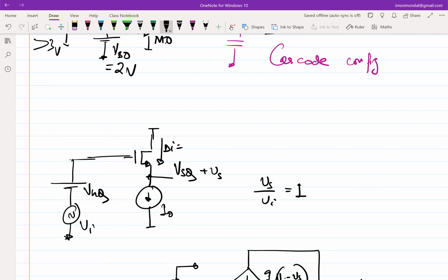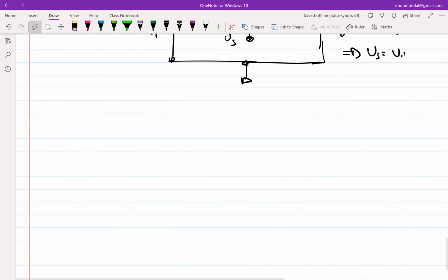It will be equal to 0, right? Because Vs is following the gate voltage, VGS is constant, so delta I will be 0. Since delta I is 0, it looks like this cannot be a common source amplifier, right? Because ultimately we want GM times Vi current to flow through the transistor, which I push into a resistor to get the gain, right? So that's a problem. If I have to turn this into a common source amplifier,